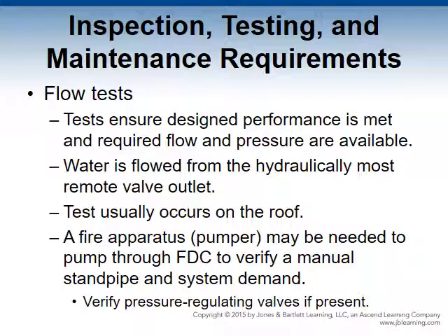Additional property protection may be necessary. A fire apparatus may be needed to pump into the system through the FDC to verify a manual standpipe design. If pressure reducing or pressure regulating hose valves are used, the system must be verified. Failure to do so could result in deficient pressure or flow. Firefighter training should include valve adjustments if conditions require this activity.